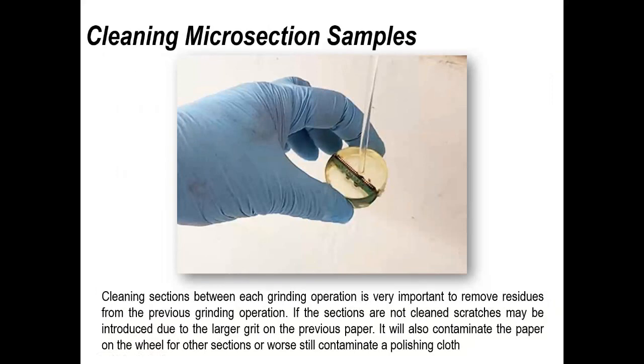The next thing you must do is, whenever you're moving to the next step, i.e. moving to a different grinding paper, or going from grinding to polishing and then polishing to another level of polishing, you must wash the sample. And please wash it thoroughly, because if you move on to another step and there is debris from the previous operation, all you're going to be doing is messing up what you've previously done. You've been adding debris, which will add grooves and scratches to your microsections.